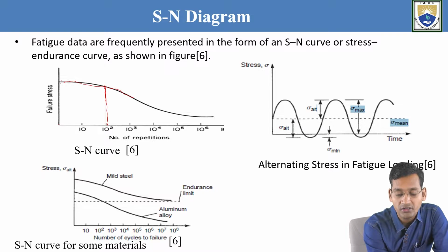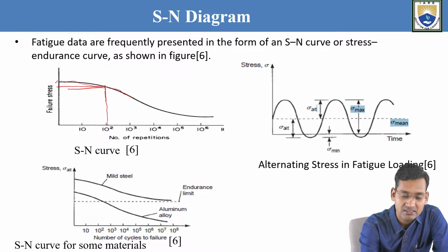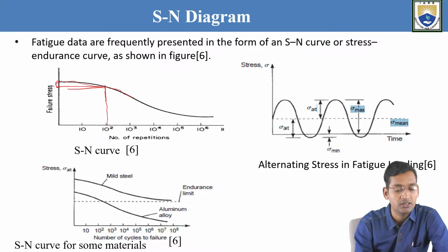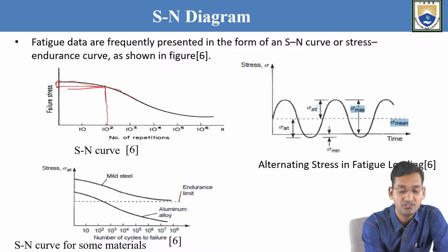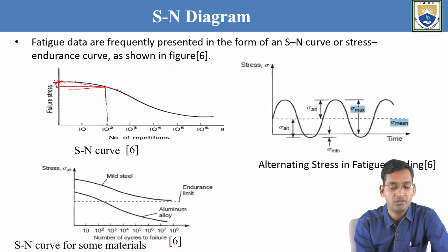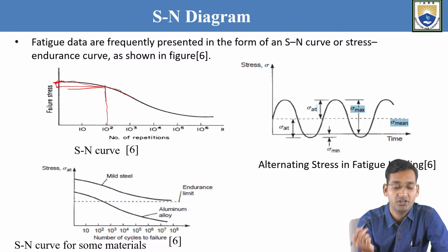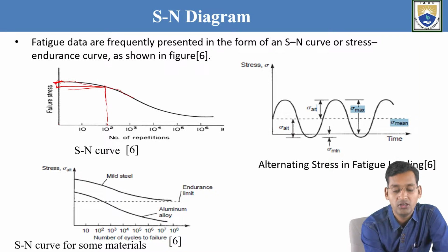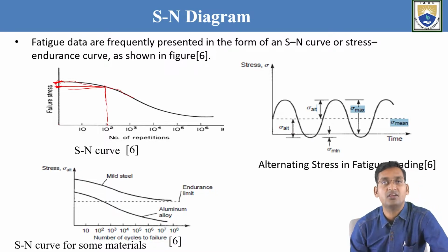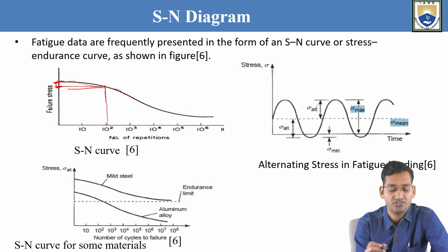So now what is the failure stress? This only, right? So up to this. Now just see, after 100 cycles, by this amount it got decreased. Earlier, without cycling, if you applied this much stress, then only that structure got damaged. But after 100 cycles, at only this stress, that structure will fail.